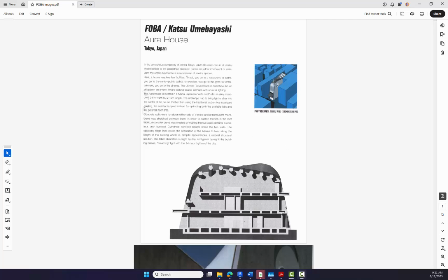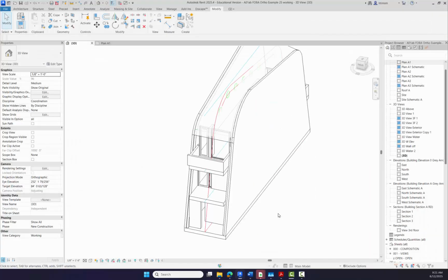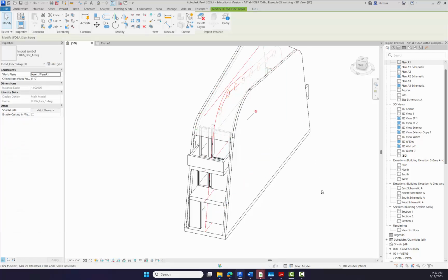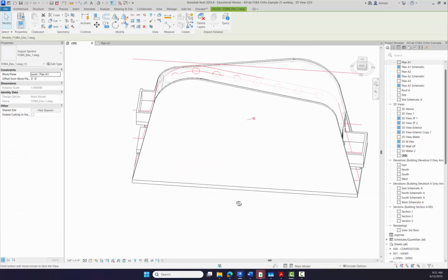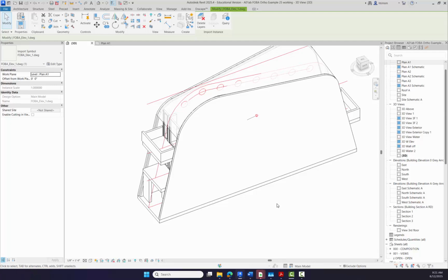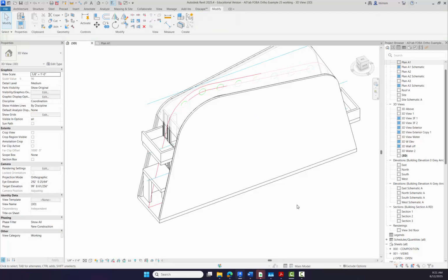All right, so the next thing we're going to do are these beams that roll back and forth between the two sort of mirrored walls. To do that, I'm going to use the component model in place again and do a blend. But what I need to do is have this guy, which is my imported piece, mirrored both ways, right?